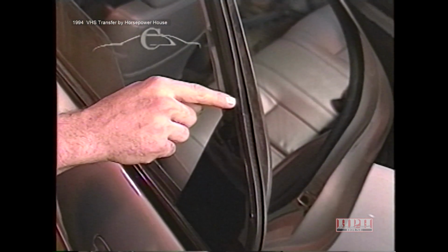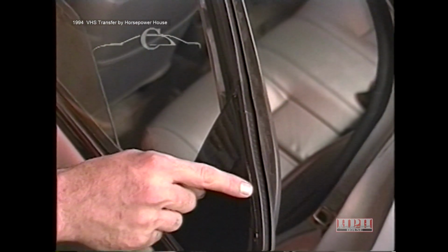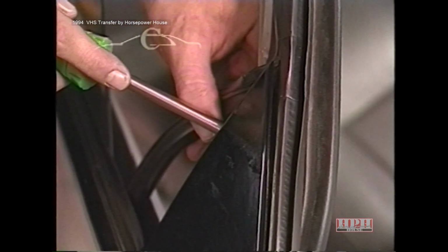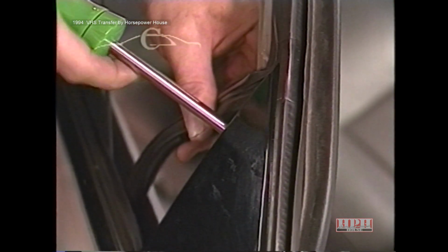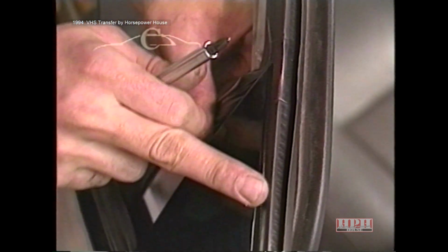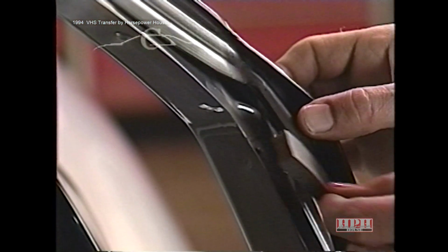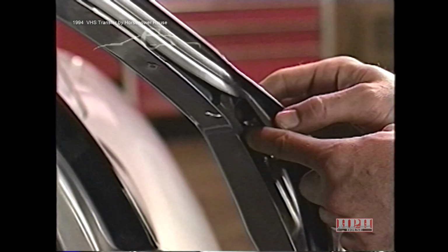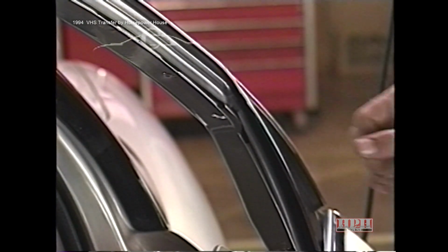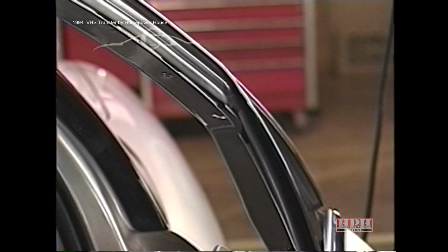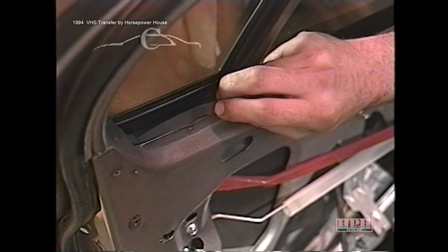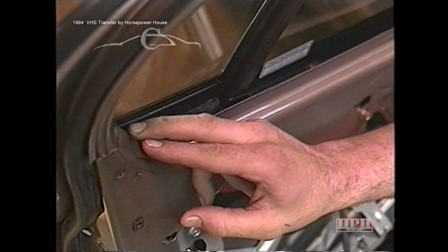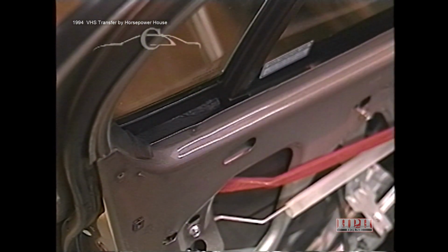If a hissing is present at the rear of the rear door, check to see if the rear door flag is properly aligned. Similar to the mirror on the front door, the rear door flag will need to be adjusted. If the hissing remains or if the rear door flag was aligned properly, apply foam tape between the outer door and weather strip at the glass run. On Chrysler, New Yorker, and LHS models, realign the foam tape behind the fixed vent window. Also, cover the hole between the inner belt reinforcement and inner panel with a foam strip.